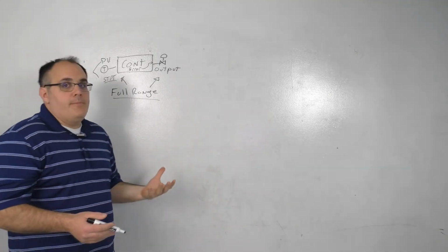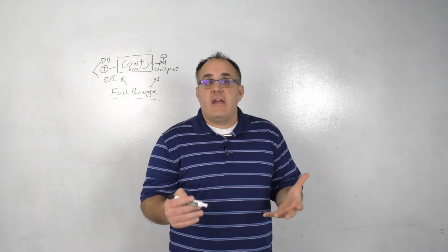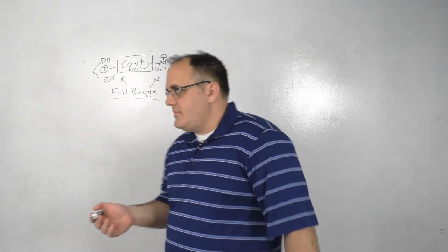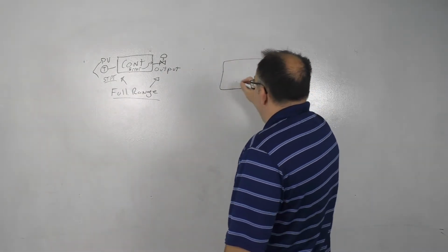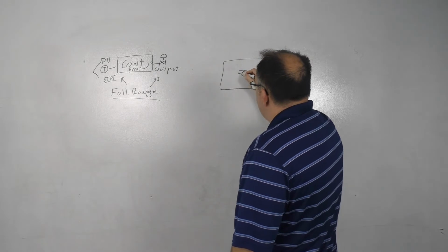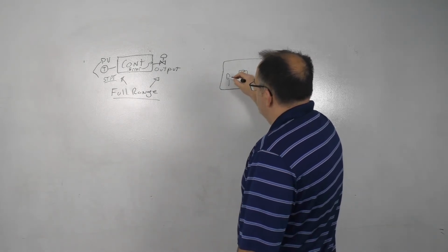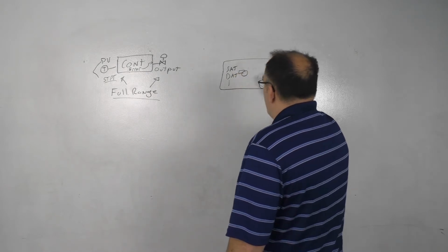So for example, our first optimization strategy is supply air temp set point reset based on load. Now typically it's an air handler, and this air handler has a discharge air temp or supply air temp, depending on what you want to call it.